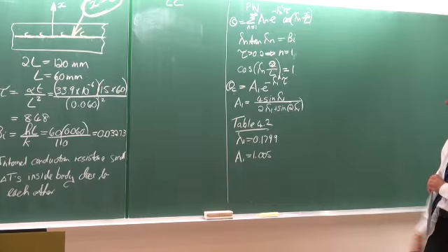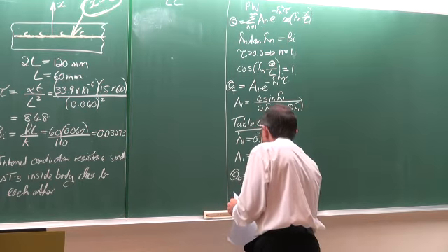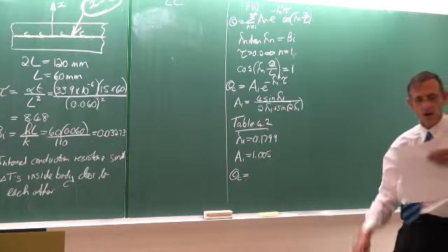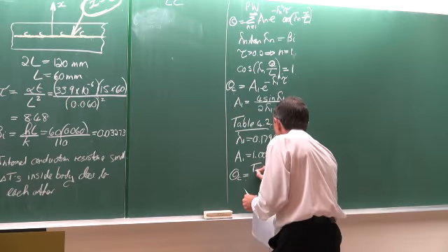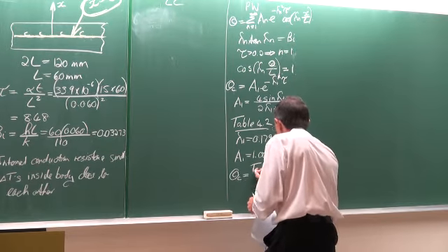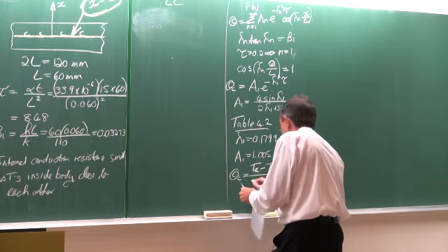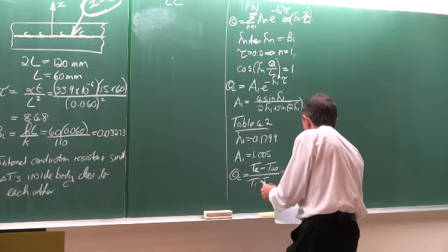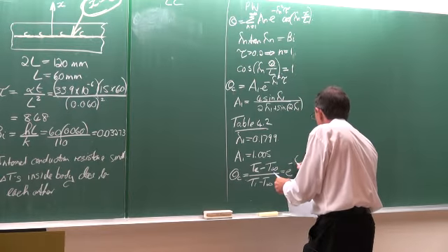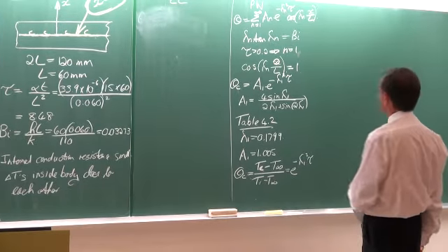Okay. Now we can solve the non-dimensionalized temperature on the center line, which is equal to the temperature at the center, Tc, minus T infinity, divided by the initial temperature minus T infinity, is equal to e to the minus lambda 1 squared multiplied by tau.